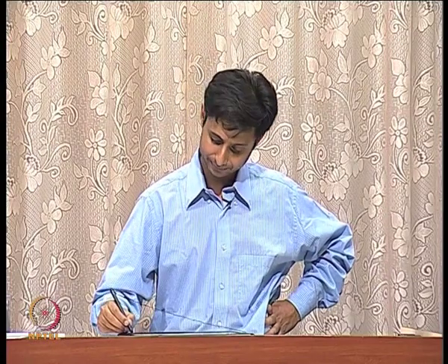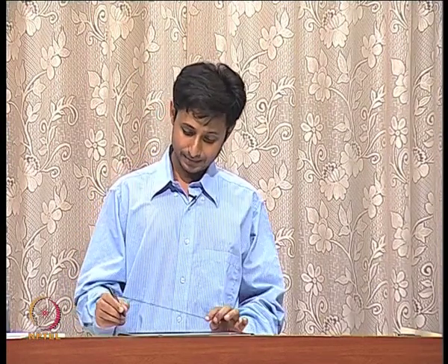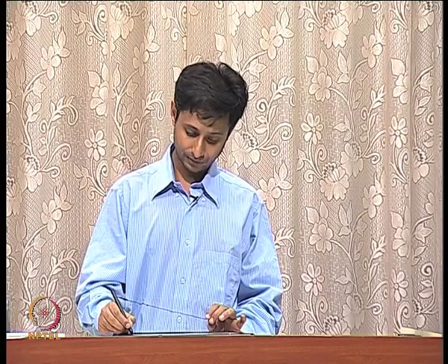This phenomenon is called the Miller effect, right. So, it is as if Cgd is being multiplied by the gain of the device. I have a gain of 10 for my device, and the effective capacitance now for Cgd is something like 10 times 50 femtofarads. So, 500 femtofarads instead of 50. Now, that was really bad news, and that is basically what causes problems.